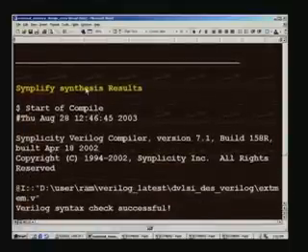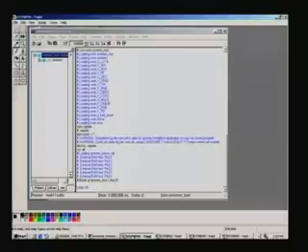So before we see the synthesis results, we will have a look at the waveforms. The first thing we had was the ModelSim result. You can see that external RAM test is passed. So it is a go no go test. This is how it reports here. Had there been any error, it would have mentioned fail and the corresponding location. And you can just zoom here.